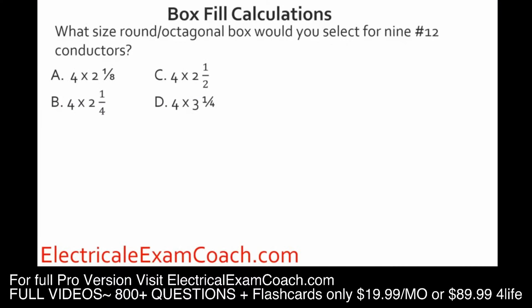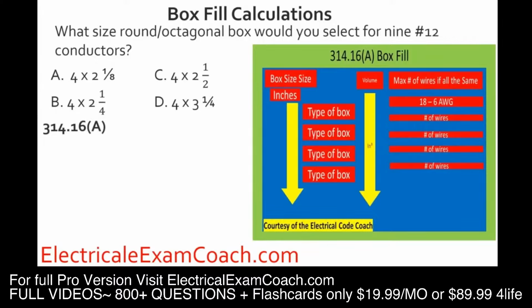What size round octagonal box would you select for 9 number 12 conductors? For this one, we're going to be using table 314.16(A). We're going to start here and find our gauge of wire. Then we're going to come down and find a box, making sure to cross over and double check that we don't cross over into a different style box. We want to stay in the round octagonal. We find our conductors, we find the one that fits, we slide over and double check ourselves, and we're going to select A. Great job!